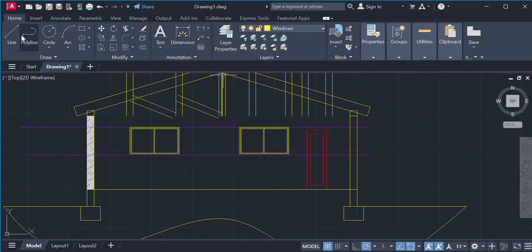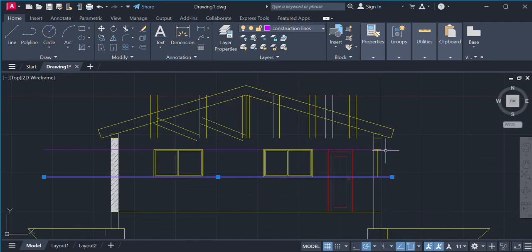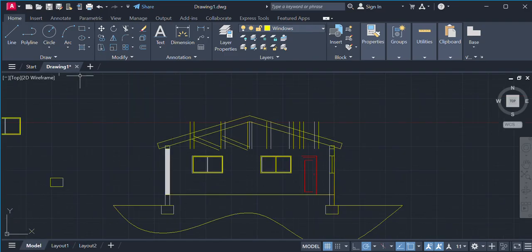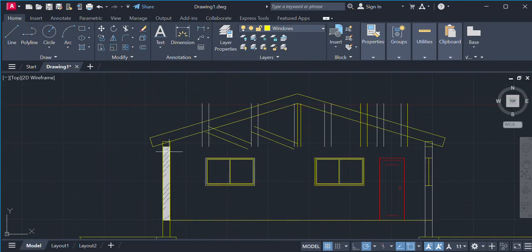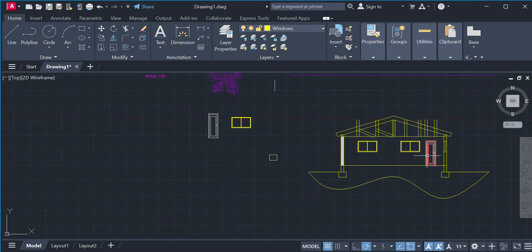And we're essentially gonna create a polyline on here, because in that position we don't have a wall, it's a window. Then we can create this to represent a window. And that's that. And next we can hatch. And then that would be it.